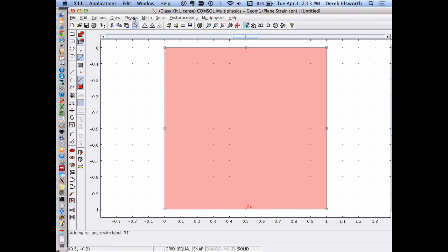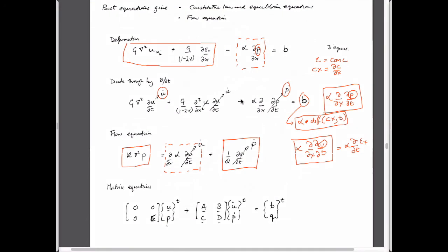And just to reiterate, basically all we're doing is in the solid mechanics equations, we're applying a body force. And so that's kind of apparent here, is that in these equations, this term here is just a body force that's being applied to represent this behavior here. And in the flow equations, we're representing a term that allows us to be able to squeeze fluid out of it to represent the fact that displacements will cause this change in the continuity relation, mass conservation equations. And really that's ultimately what it is.